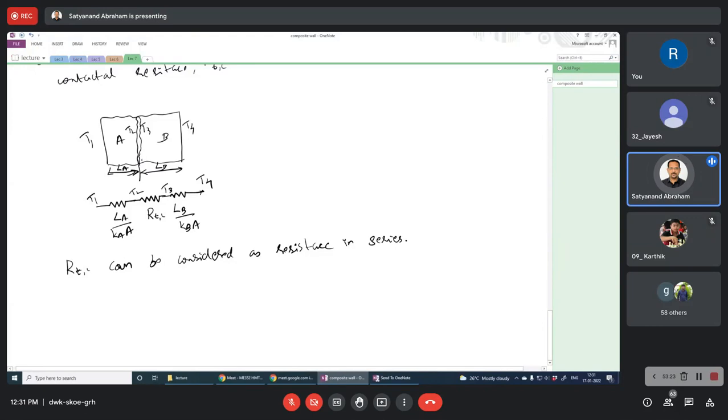For different materials there is a minimum roughness that is practically possible, so the combination of materials also influences the contact resistance. Therefore, R_tc is measured using experimental studies, and usually experimentally determined values are what we use in most cases.